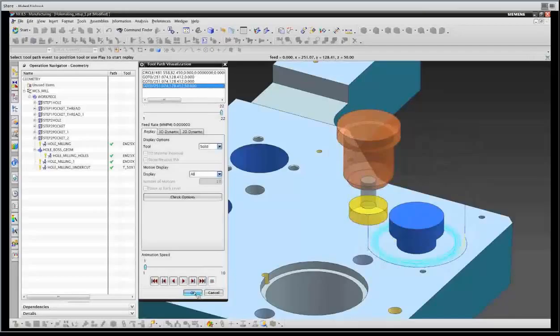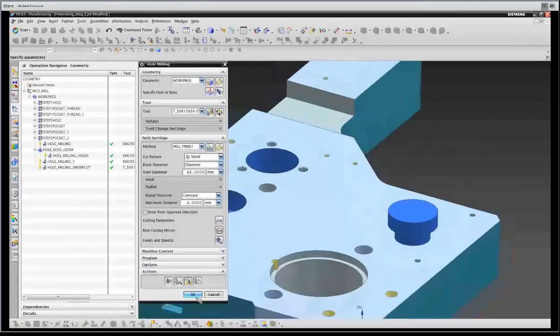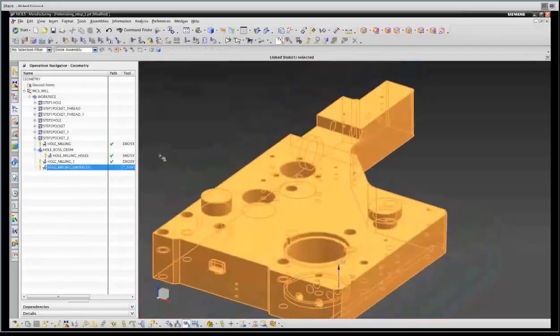So for undercuts, whatever type thing, this processor works well with that. We have the 3 different options of spiral cutting, helical cutting, or a combination of spiral and helical cutting, where it makes sense. Now let's go do a little bit of thread milling.